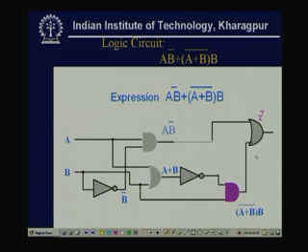So, in this way, what we have done is, if a Boolean expression is given, then we can draw a logic circuit, that means a number of logic gates with the interconnections, so that it realizes that expression. That means if I give the input values in terms of zeros and ones, the logic circuit should evaluate the same output value as the expression for the same input set, and then we can tell that the Boolean expression is correctly converted to the logic circuit.